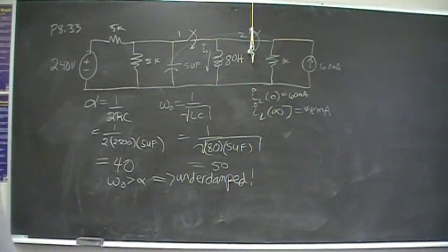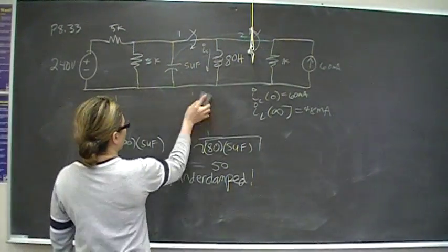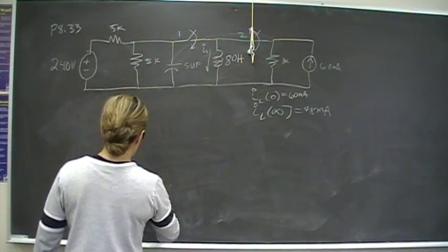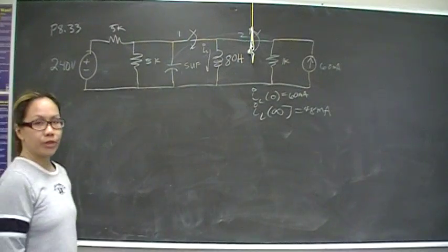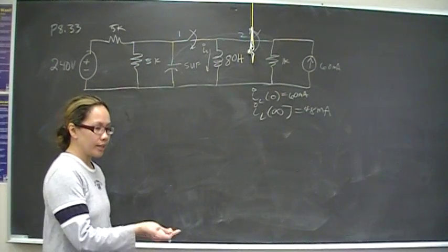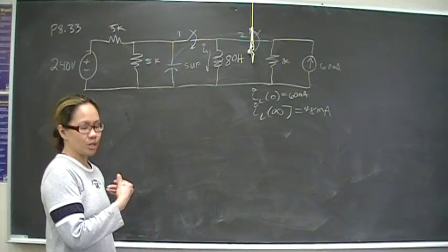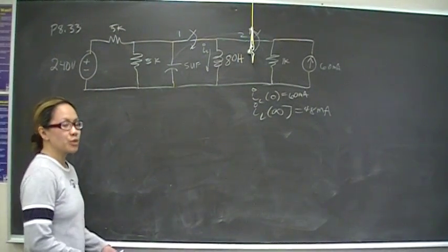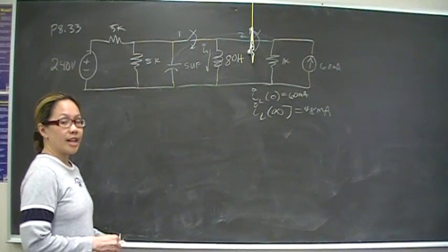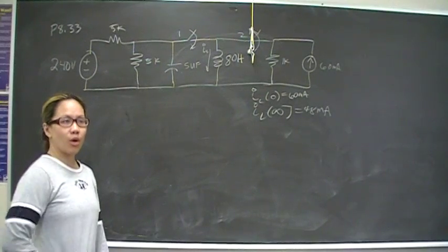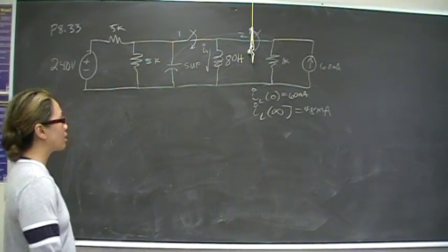So then we look in our book for the equations for an underdamped response. And these are the 3 equations that we are going to be working with. And instead of dx/dt, I'm just going to write down what it is we're looking for. The x is just a general variable placeholder for the engineer to plug in. This is going to be dc/dt, dv/dt, di/dt. So what's really super cool about this is that you have a general equation that describes it for everything. And you just have to know what you're looking for and what the initial conditions are.